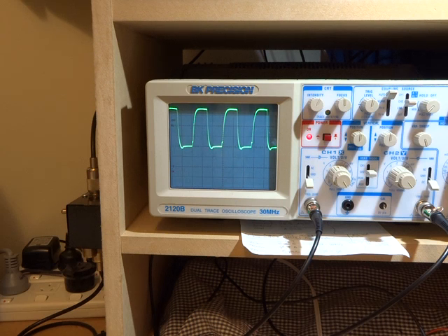That is the input to the low pass filter, and that would be being fed then through to the RF power amplifier, which would not be good. Put the earth back on again, and as you can see, it just cleans it up really nicely, which is good.